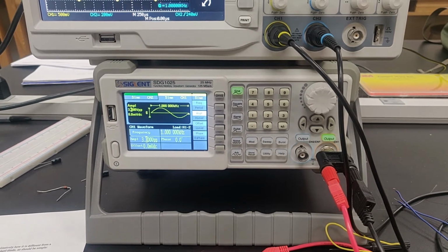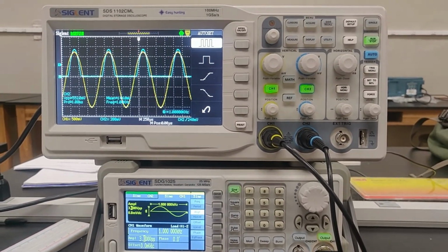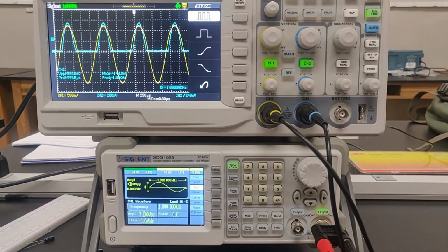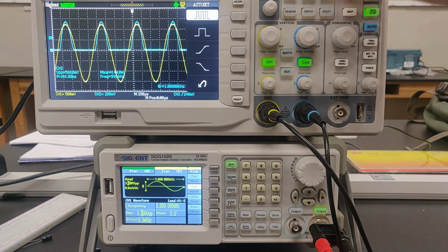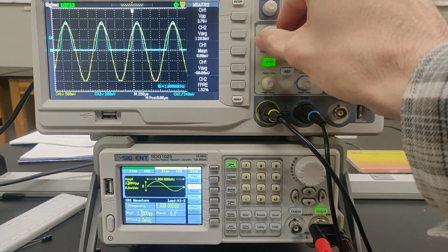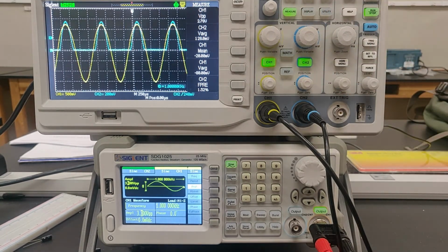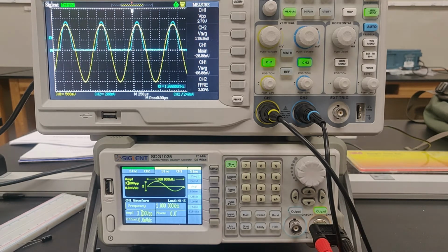And so let's take a look at this first circuit. So I've constructed this circuit on figure 6, which again looks like the forward biased circuit, but now that we're using an AC signal, it's also known as a half-wave rectifier. So right now, let's see what's happening. Oh, and I'll point out that our yellow channel, channel 1, is our input, so just the sine wave that we're getting from the function generator. Our blue channel, channel 2, is our output.